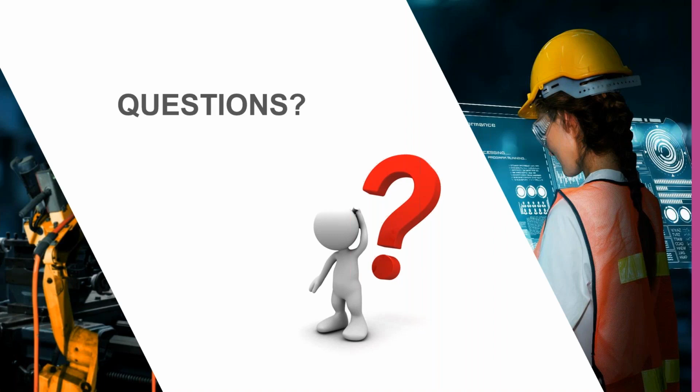And I just wanted to show what that would look like, using the dimensions as an example, because that's the same process you would do for other annotation types as well. It's all the same in terms of you select what type of annotation you're doing, and then you're selecting references, and then you're creating a new annotation that way.